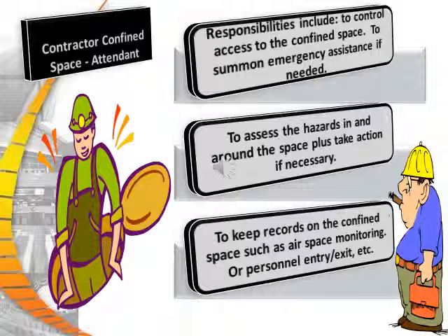Responsibilities include controlling access to the confined space, summoning emergency assistance if needed, assessing the hazards in and around the space, taking action if necessary, and keeping records on the confined space such as air monitoring and personnel entry or exit, etc.